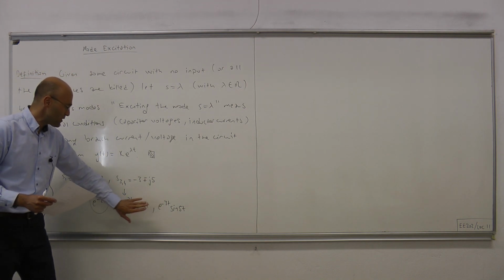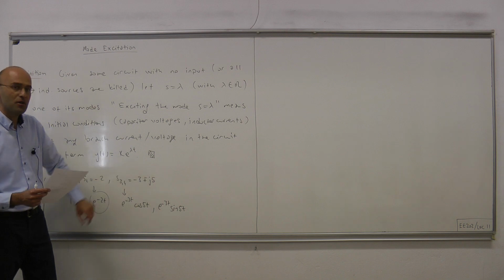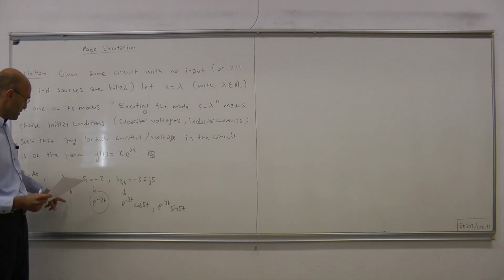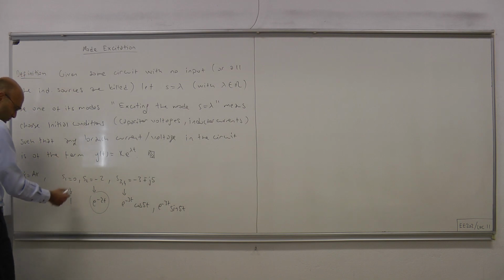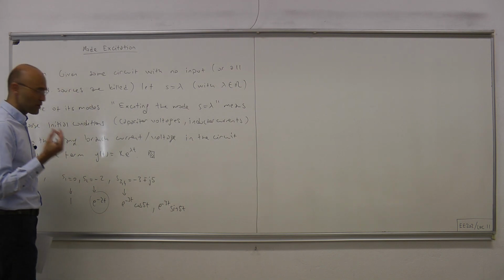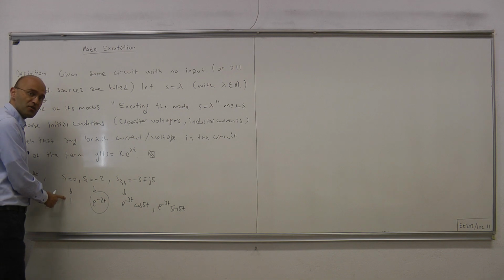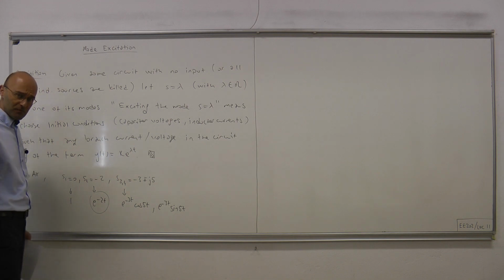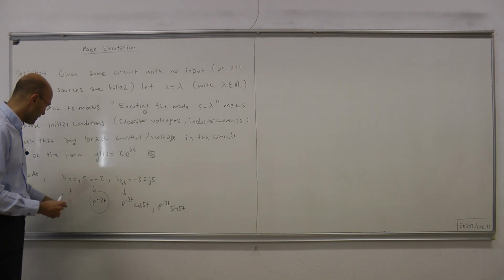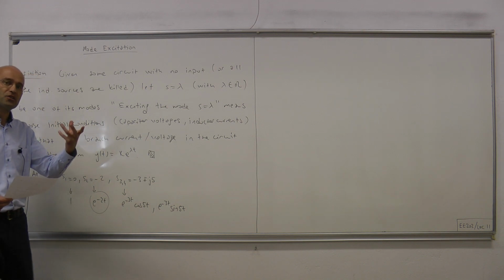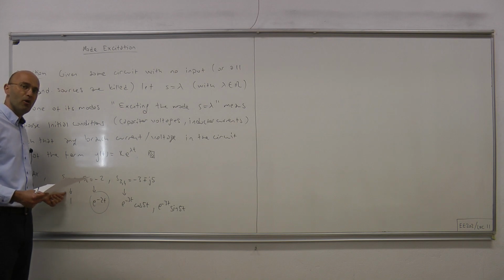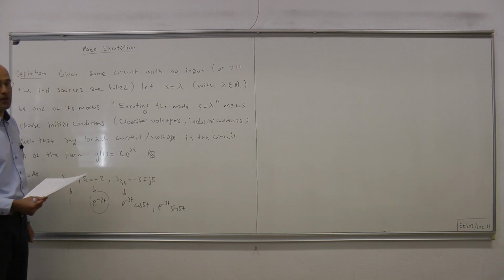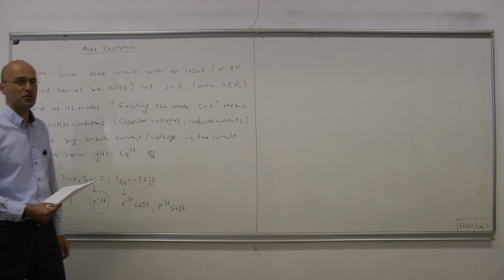That is, we want to suppress the terms due to this pair of modes and this mode. Or we want to choose the initial conditions so that all the currents and voltages in the circuit, at the instant that we start the circuit, are all constants. So the circuit already starts in steady state. That's also possible because we have a natural frequency at s equals 0.